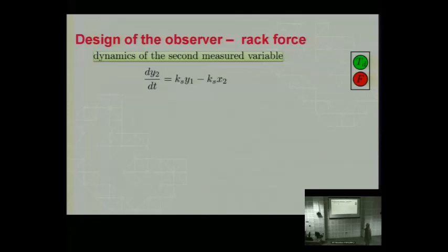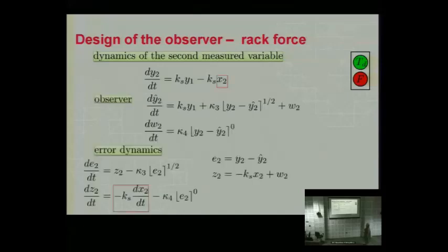So we said, well, the rank condition doesn't hold, and so we can't get F from Y2, but let's get what we can get. Let's get X2 from this observer. So away we went, designed what's a higher order observer, got finite convergence time of E2, and managed to get X2, which was an added bonus. So we had X2 now as a signal exactly from our observer.